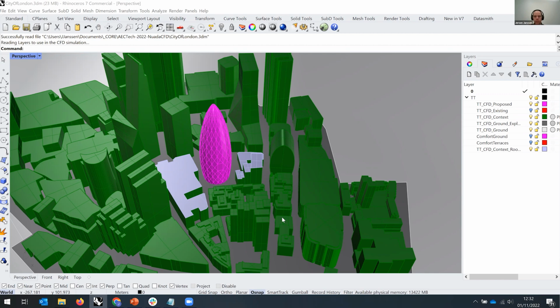So you would get all of your results and you can then scale that up to whatever it is, your 30 meters per second wind speed for a Eurocode or your 70 miles an hour for the American code, let's say, because they also multiply slightly differently. The Eurocode looks at mean wind speed, whereas the ASCE looks much more at peak wind speed. So there are different things in that.